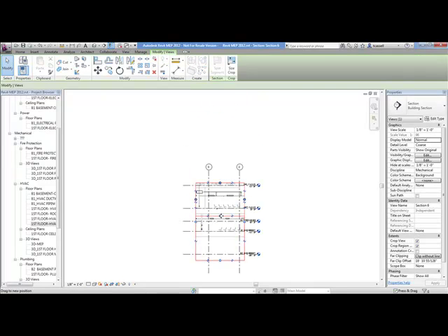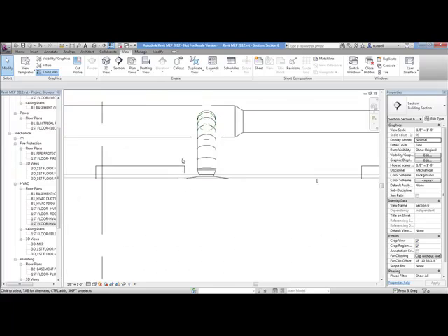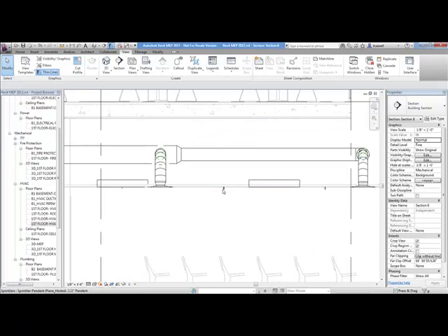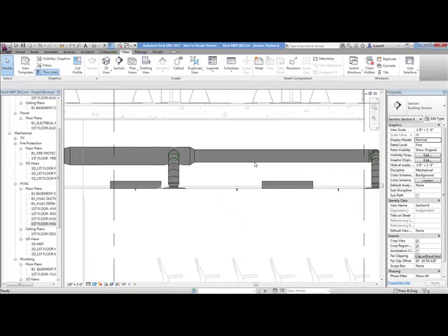Now I'm only focused on the first floor, so let's show the first floor and take a good look at what we just drew. So this is what we just drew, and I'm looking, yeah, I'm a little close to that light, but is that a collision? I don't know. I might be okay with it. You see some sprinkler heads in here, and if there was piping or fire protection running through this area, if there was plumbing running through this area, you could see all those pipes and you could visually check for any collisions. Now let's assume for just a moment there was going to be a collision or a problem here.